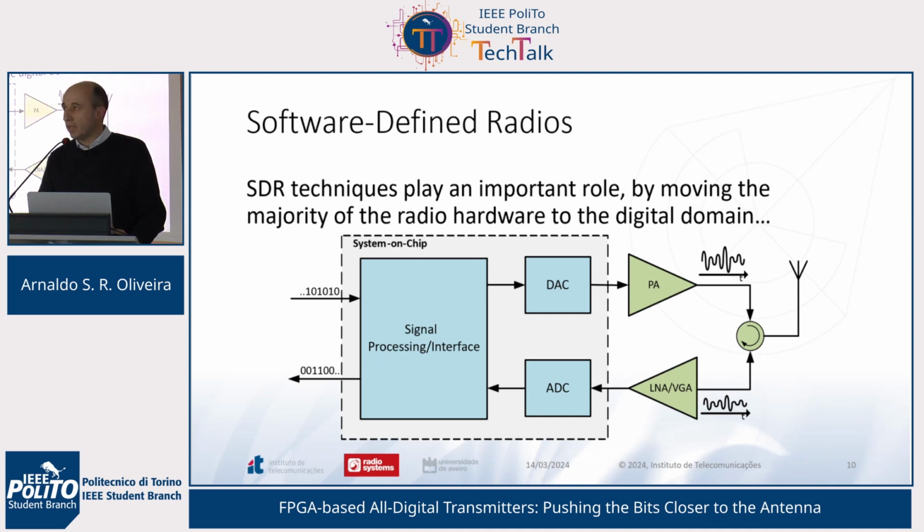transmitters. The idea appeared challenging because when we apply pulsed modulators to the analog conversion of a digital signal, we need a considerable oversampling ratio, and if we are talking about radio signals, we will have to deal with considerably high frequencies.